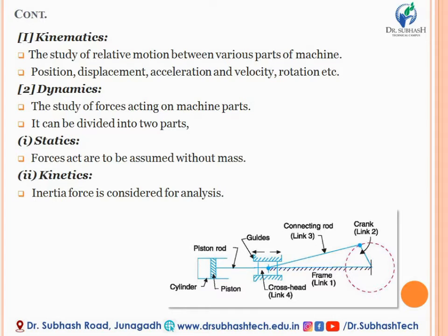Secondly, the steam force produces thrust force in the connecting rod, and by resolution of forces we can determine various forces that act on various links, either on the crank, the connecting rod, or the piston. So this includes dynamic analysis, especially static analysis.